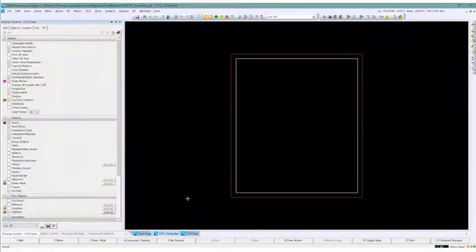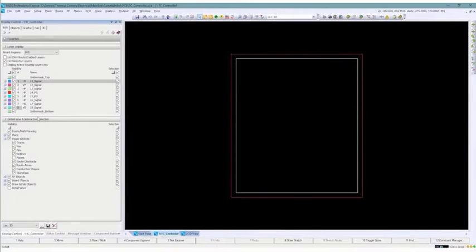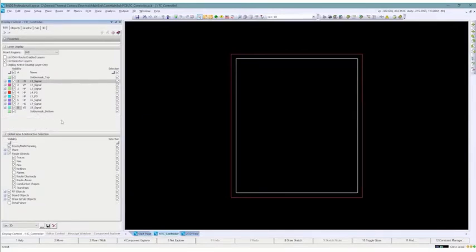All right, so here's our basic PCB that we've forward annotated our schematic information into with an 8-layer stack up that we're going to be dealing with, at least for the main part of the board. But that's one of the important things that we're going to talk about is how to define individual stack ups for the areas of the board. It's very important functionality that differentiates a basic PCB tool from one that has flex centric capabilities.